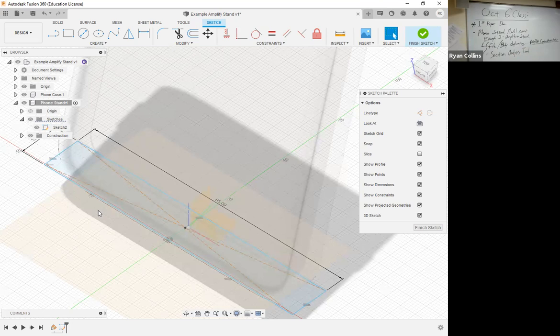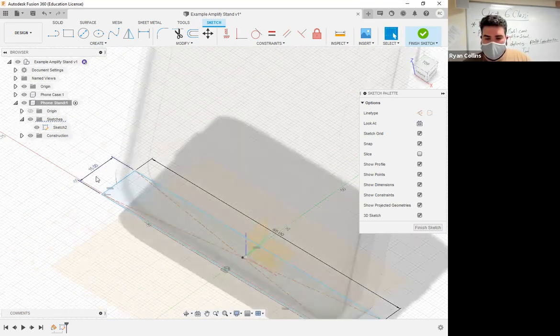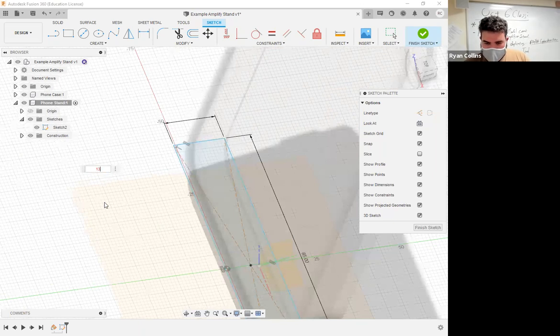Have my calipers on hand just to double check my dimensions. So let me double check those dimensions for the shell of my phone here. 80 by 12. All right, cool. So it's about right. It's a little large. Remember, you can change that by double clicking on the existing line there. So 15 will make that more of 13, and same over there. What's going on? No, I just want 13.